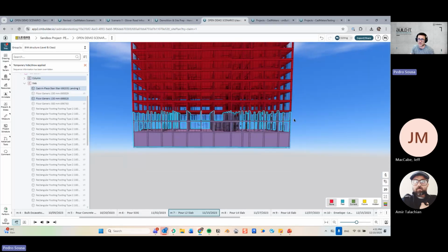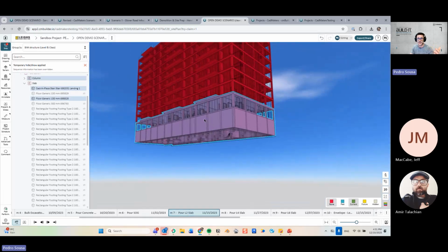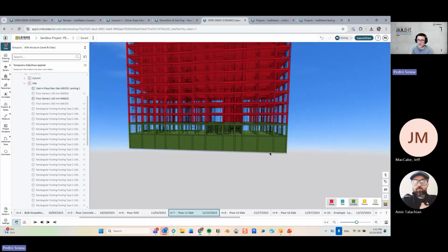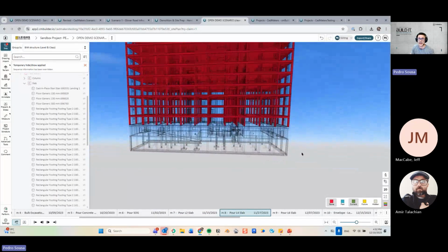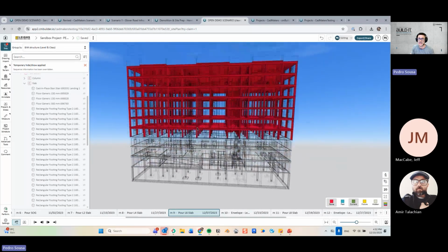So I can now select a bunch of parts and say, I want to show all the elements up to level 2 slab on this milestone. So I will set that this should begin at this milestone, and you see that the object becomes green because it now belongs to the current milestone, right? So that way I can very quickly finish my simulation just by selecting a bunch of parts and then assigning them to the correct stages, right?